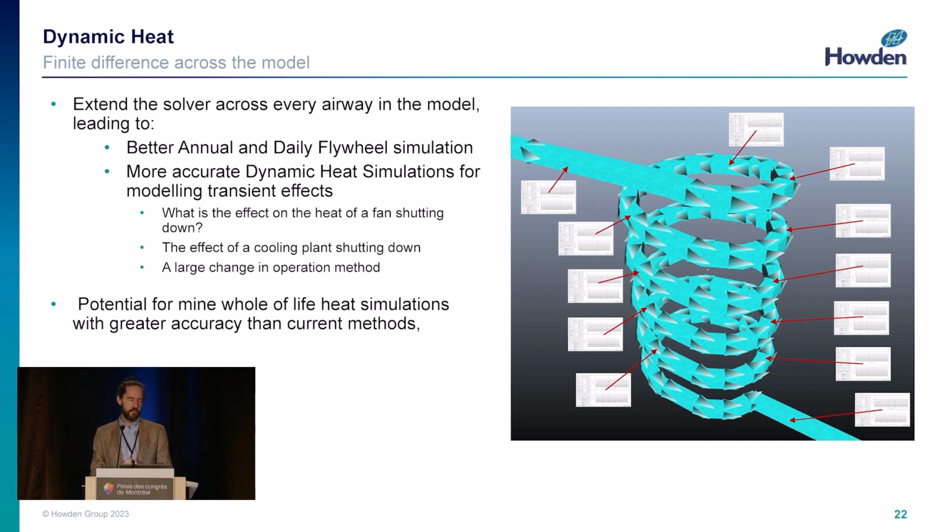If you imagine you've got a fleet of diesel vehicles running up and down a decline for many years, and you swap that out with something like an electric fleet, or you replace the work that fleet is doing with a hoisting shaft, that's going to have a big change in the heat. There'll be a transition from one state to the other, and knowing what that transition will look like is quite difficult to model at the moment.